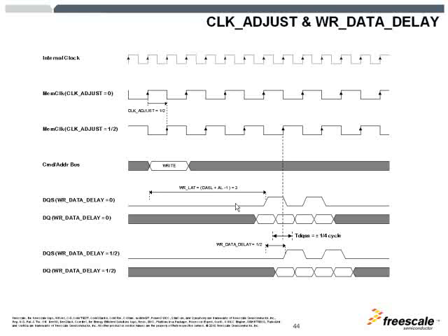The next item here is write data delay, and write data delay is shifting the byte lanes to compensate for the TDQSS requirement by JEDEC. So the strobe and the clock are not way off from each other, but maintained within the quarter clock.